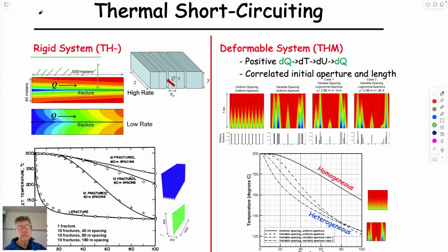That means that the change in temperature with direction times thermal conductivity is equal to flow rate. Since the flow rate at this boundary is going equally much in this direction and equally much in this direction, at this boundary the gradient of temperature orthogonal to it has to be 0. Thermal conductivity is not 0 at this boundary because it's a part of a whole system.